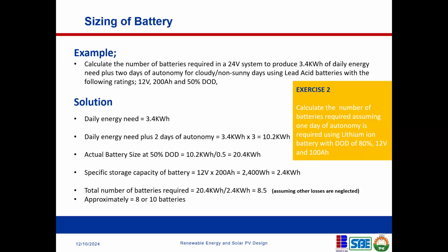You can only know this for sure when you have deployed your system and actually take readings. Now, there are factors that affect these losses. These are not cast on a rock, but you need to put on your thinking cap to estimate the level of loss. Let me give you an example. If you have a battery system that is installed in a high temperature region, and the temperature of your battery storage is high, then you should anticipate more losses.